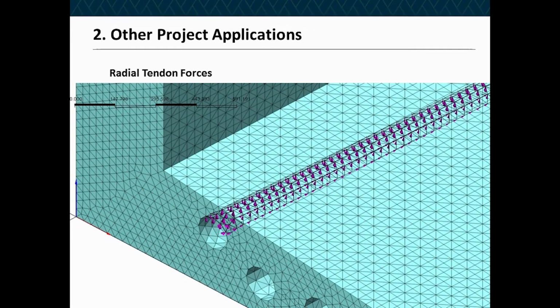Now, as part of our investigation, we embarked on a solid model within FEA again. We were able to model the duct line perfectly within the solid and extract and subtract that using the Boolean commands, and then we were able to mesh that solid to give us the concrete with the duct in.